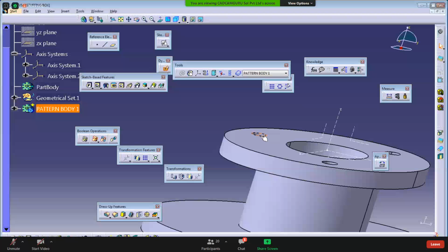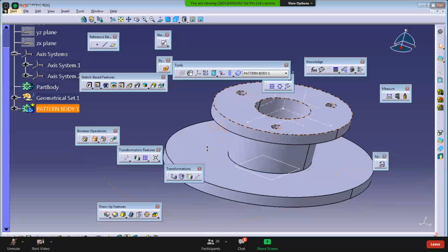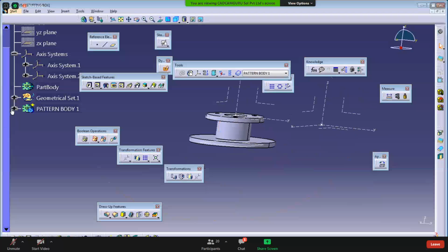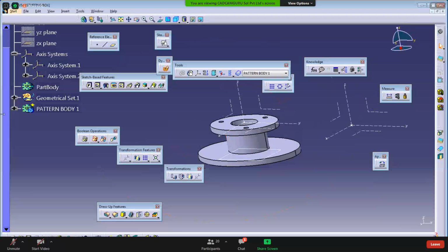But in your last example, in the Boolean operation, the threaded hole was very hard, so we had to do it as separate machining. Here, no need to create a machining feature separately. You can add it directly inside the core. All right. So the results are created. We can see the section by taking this dynamic sectioning option, take the plane, you can see that. And this finishes my model. That's it.